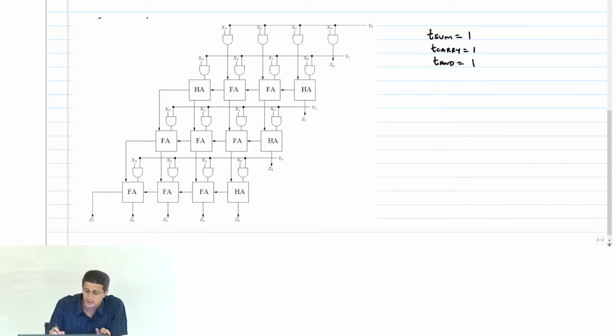So now let's do a static timing analysis on this block and propagate these signals to the half adders, and assume everything is a full adder now. Okay. So the arrival time at the output of every AND gate, at least the first AND gate, is what? Actually every AND gate. Yeah, because all x's and y's arrive at time 0, right?